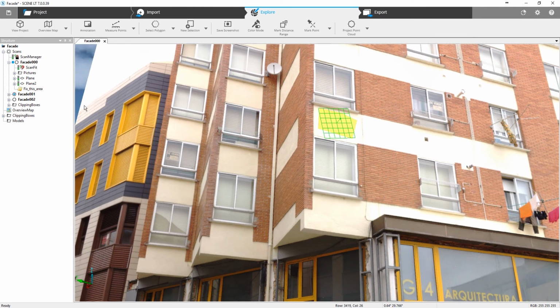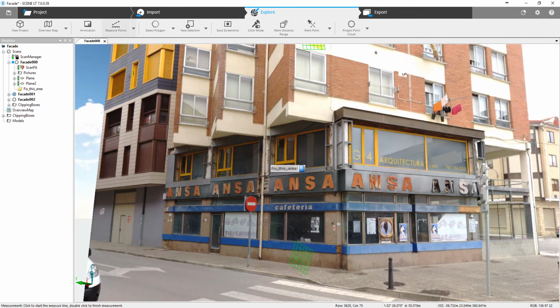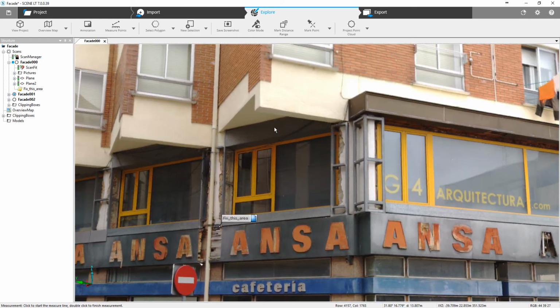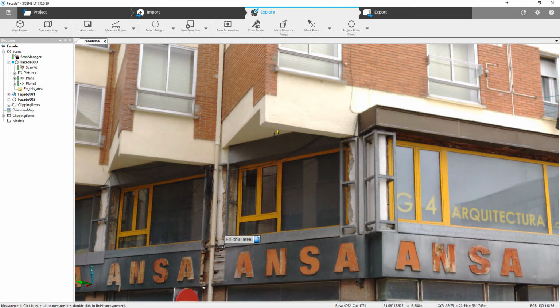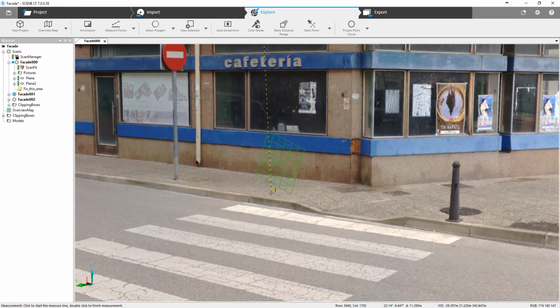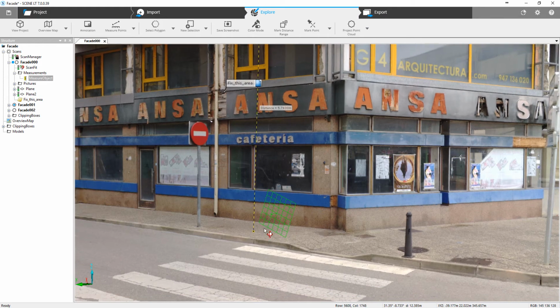Okay, good. More things that I can do. I can take any kind of measurements, just measure points. I can make a click here, for example, or imagine that I want to know which is the height. To do this I need to hold Control key, because if not I cannot even zoom in, zoom out. But if I hold Control key, and now I want to measure up to that point, press enter. Here we have the distance is 5 meters, 0.74.